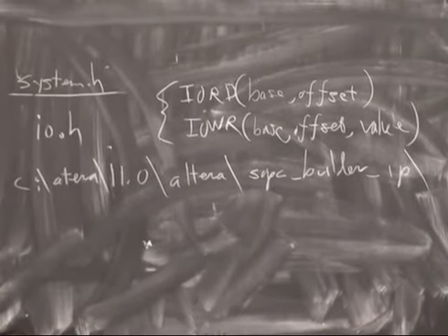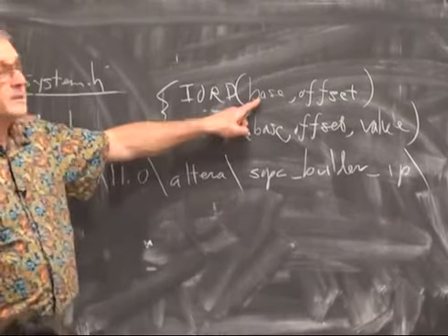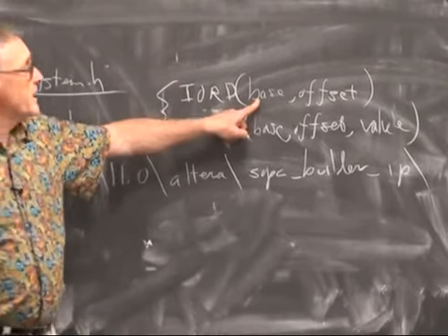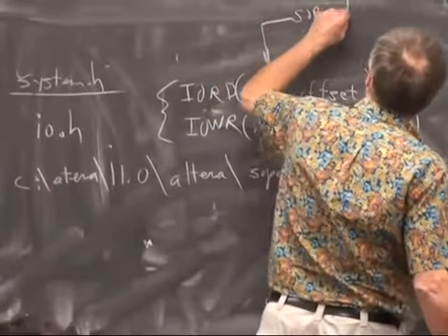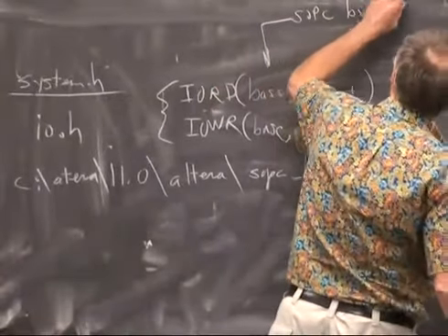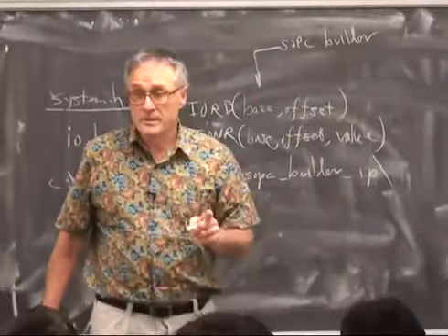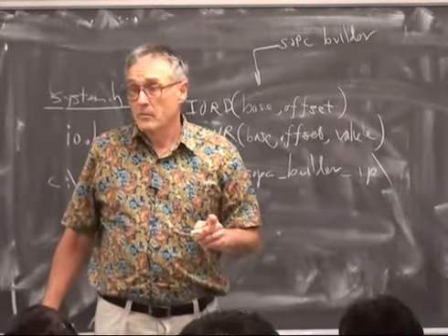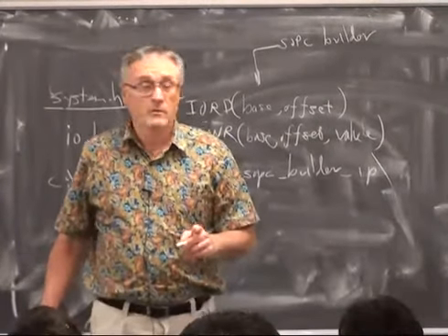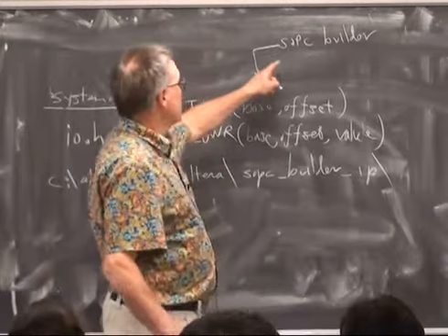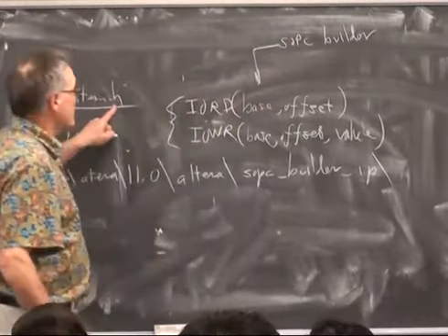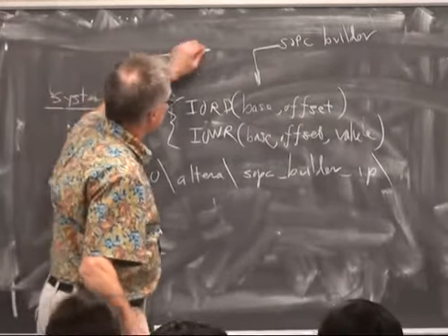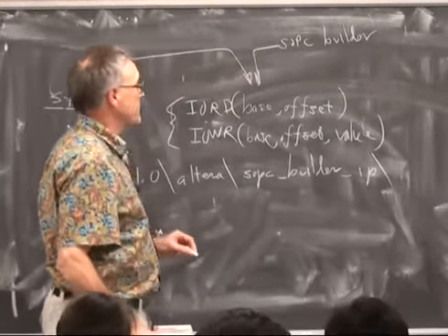The base address is assigned by SOPC Builder, and you can read it in SOPC Builder, but you shouldn't. You should use a symbolic version, which is in system.h. So system.h is going to supply the base address.